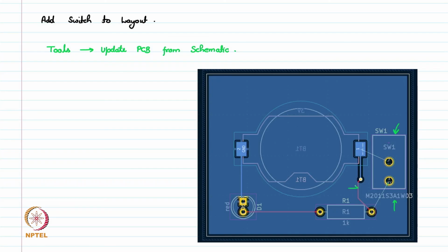So what we need to do is remove these already existing connections and route these extra two red nets using the metallic layer, front copper or back copper. So we delete the earlier connections and then route the new traces.